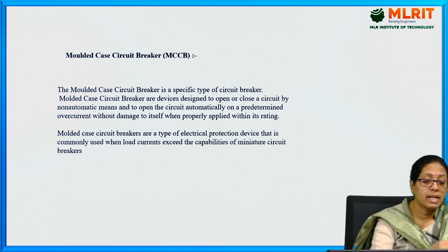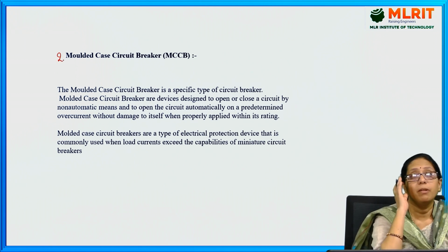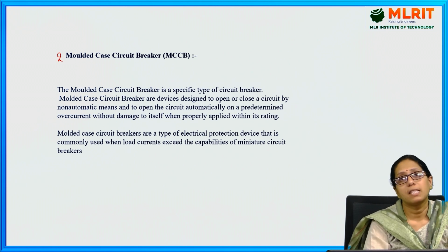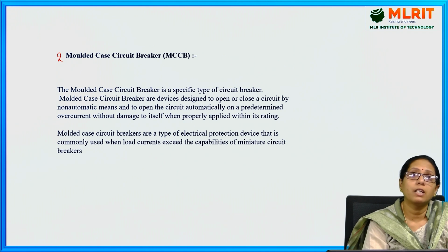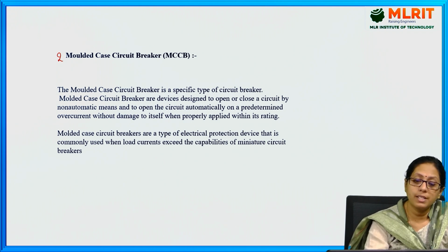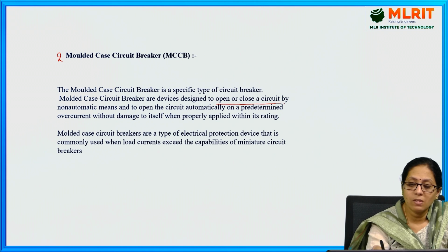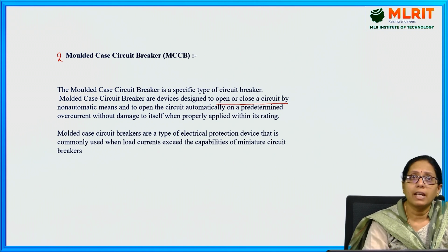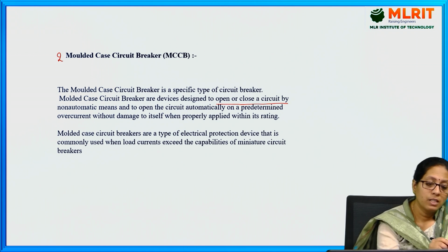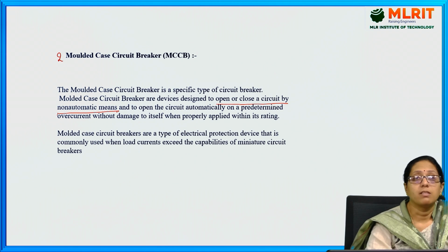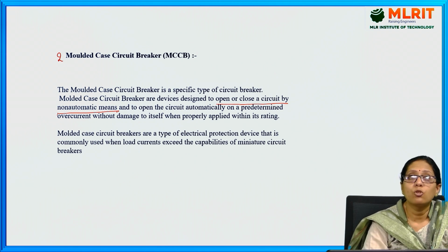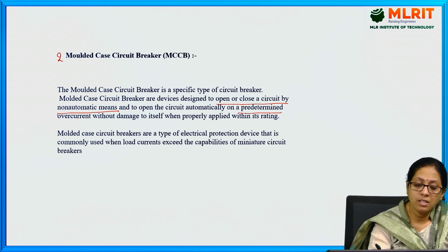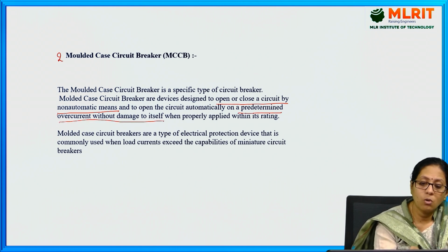The next, second type is MCCB, that is molded case circuit breaker. The molded case circuit breaker is a specific type of circuit breaker designed to open as well as close the circuit by non-automatic means, and to open the circuit automatically on a predetermined overcurrent without damaging.